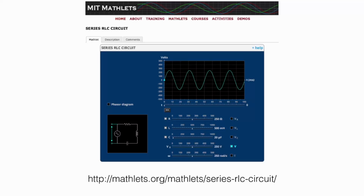Notice when we added this capacitor in series, in the AC version, do you see how those two curves are offset? They're not happening at the same time. So again, if we play our thing there, and we try to measure what's going on in the circuit, the capacitor and the resistor are doing different voltages at different times. I don't want to get into why. I'm just pointing out that this is what happens.